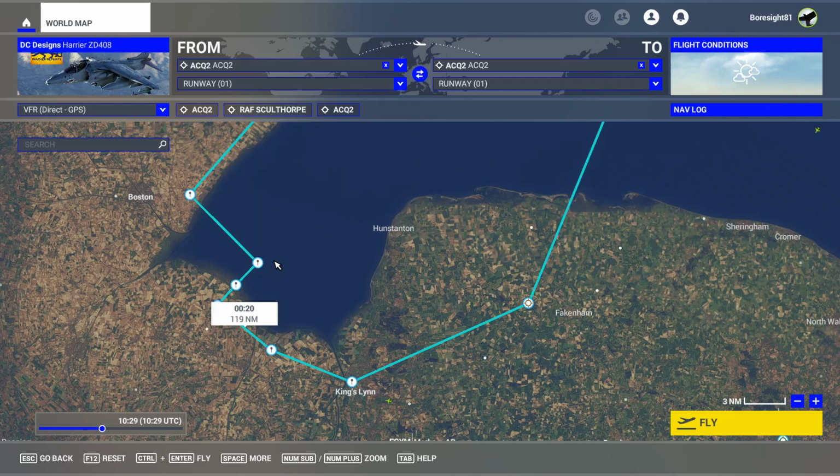what it does is it takes in the aircraft's altitude, speed, angle of attack, things like that, and then it will calculate an impact point, and on the HUD you'll get a vertical plumb line, and at the bottom of that plumb line is where the impact point will be. And what you do is you just place that point on top of the area you want to bomb, and you keep it steady. Once you get to bomb release point, you pickle all the bombs and then you get out as quickly as